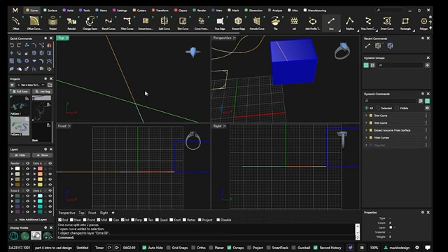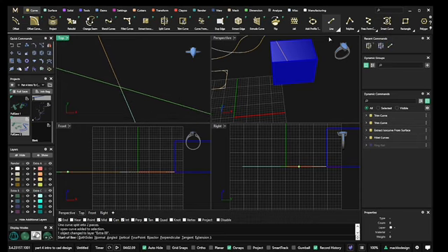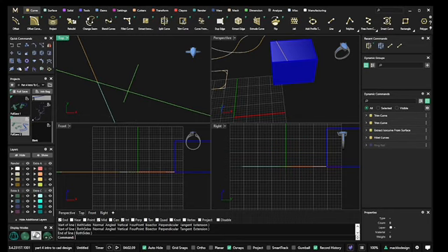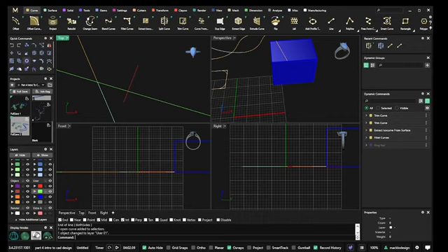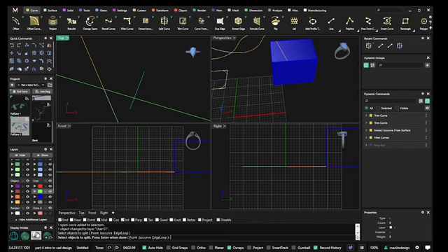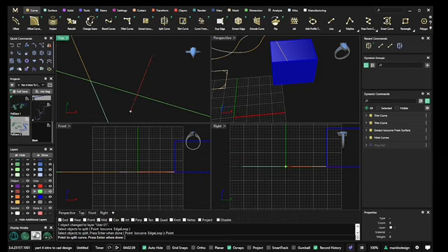I'm going to put one more line here because I want to show you how this works. Turn it red, how it works with your quick command split. I'm going to select split. I want to cut this line or split it, and I'm going to do it with a point. And my intersection is on, and look at that. It grabs right there at the intersection. And I click, and then I press enter when I'm done, and it split right there.